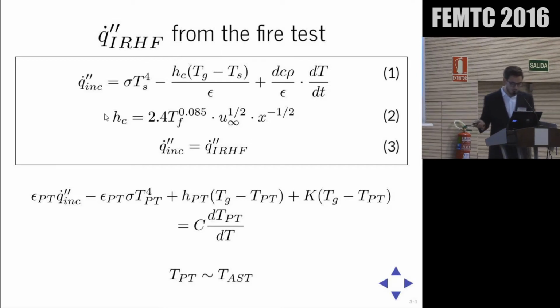The far left term on that one describes the radiant heat that is absorbed by the plate. The second term is the heat that is emitted. The third term is the heat lost by convection. And the fourth one is the conduction, the heat loss through the insulation pad and along the surface. The term on the other side is, in a simplified way, the rate of heat stored, calculated by lumped heat capacity. So by neglecting the conduction loss and moving around the terms,